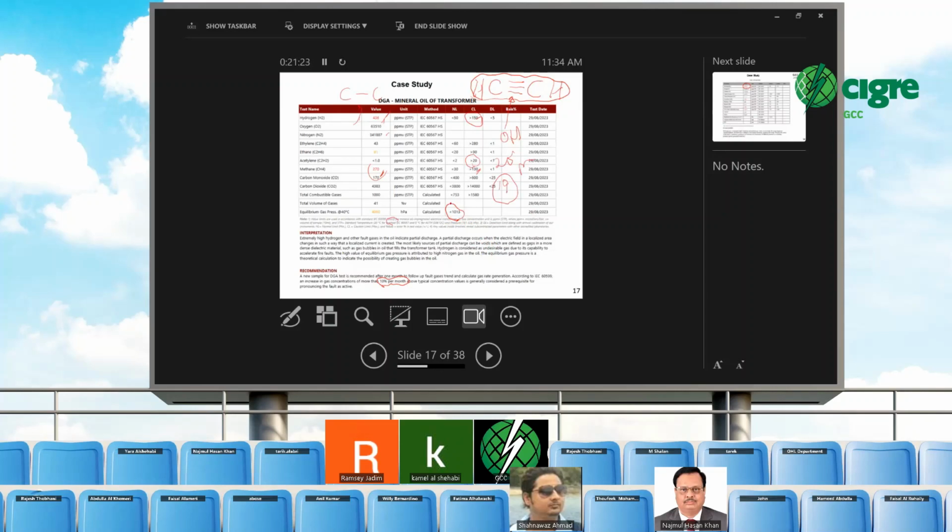This limit was derived from about 1000 transformers in research, and they keep this 20. It is not fixed. Usually, if it is 19, I see it as very dangerous. What we found, there is an equation in one article that tells you that you have a problem. It is not at 20, it is something before.